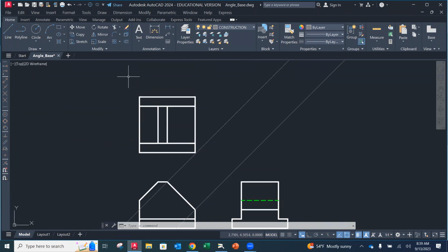So the beauty of CAD is I can simply move that. Now, I do want to put my ortho back on because I want to keep it in orthographic projection. So I am going to grab the move command. I am going to window around. Don't drag, click, click for upper left, lower right. I'm going to enter, and then I'm simply randomly out here. Try not to go close to other things, because then it's going to want to snap, you know, to different things.